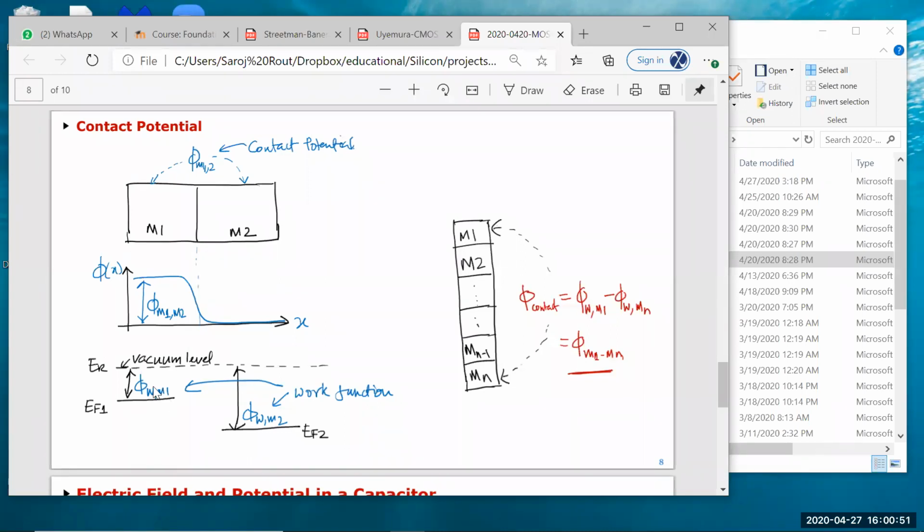Maybe I said it. So you can see from this diagram, this one has a higher Fermi level than this side. So let's say this was metal and this was a semiconductor. Let's say this is your gate, this is your P substrate. So that's how it'll look like, right? So if you take the definition of phi ms, the electron energy is higher, but your work function is lower, because if your electron energy is higher, it takes less energy for you to get to the vacuum level.